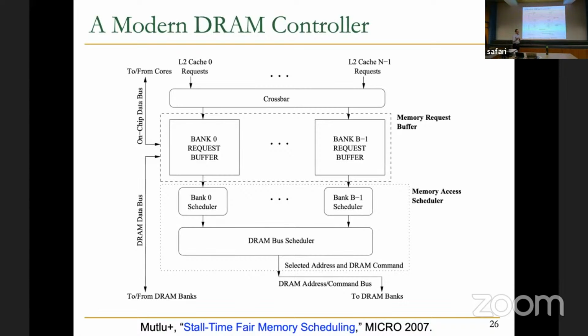So this has clearly implications as to what's happening over here, right? The CPUs are over there, and if you actually are doing a lot of switching to write mode, writes are not as critical for CPU performance, right? Because writes may be write back from the cache. So L2 cache, there was an eviction and a dirty line got written. This has in many cases nothing to do with the CPU request, right?